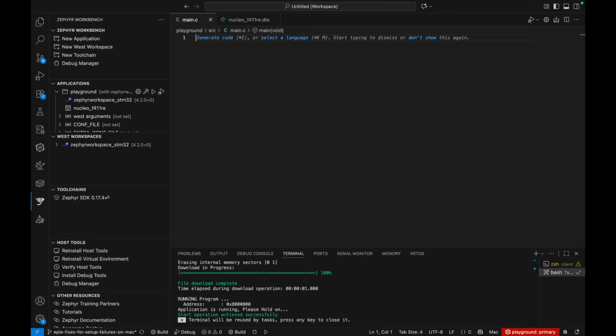What I want you to know is that in Zephyr, there are different ways or APIs for using the UART drivers. The first one which we are going to look at is polling, and then we will also look at the asynchronous mode where we will use interrupts. The advantage of using the interrupt approach over the polling mode is that it frees the CPU in a certain way. As you know from interrupts, something happens that is of interest or importance to your program and you interrupt the CPU to take care of it. Afterwards, it goes back to where it was, right?